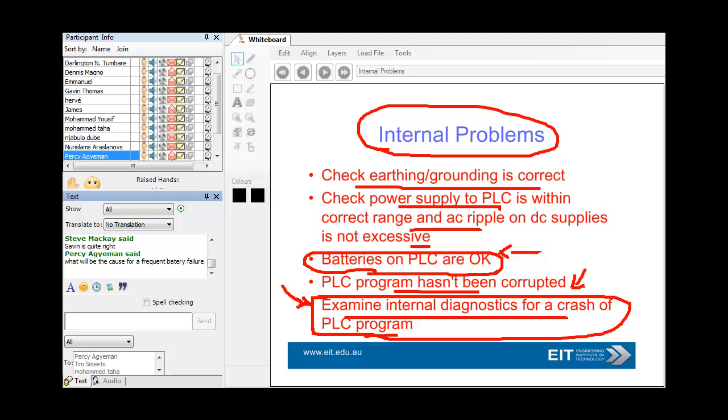What normally happens at that point, which happened to me on a mineral sands plant, the battery failed, and they had a power failure to the plant at the remote site, and they knew immediately the battery failed, because when they booted up the PLC again, there was no program. And of course, inevitably, someone had been making changes to the program for the last 3 years since I'd been on site, and of course, we got an anguished call from the client, please can you give me the program? And of course, we didn't have the changes. We gave them what we had, but it was 3 years out of date, so it didn't help them much. But they should have backed up.